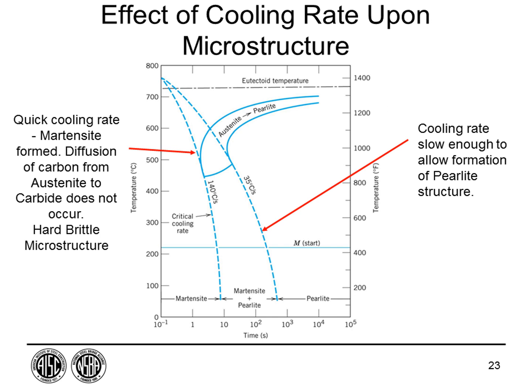So if we look at the time it takes for the transformation from austenite into pearlite, we can look at it in terms of a cooling curve. And so this is temperature shown here, and this is time in seconds this way. And these lines here represent how long it takes at a given temperature to start the austenite to pearlite transformation. And if you get to this line, then that transformation is complete. So you show two different cooling curves here. If you follow this curve coming down, you'll never transform the austenite into pearlite.